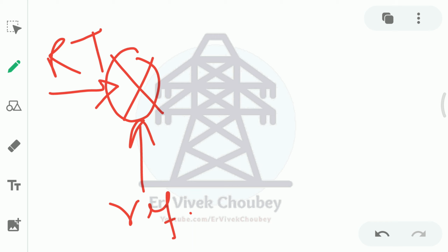Now let's say the room temperature is 25 degrees Celsius and the reference that we are setting up here is 20 degrees Celsius. So there is a temperature difference of 5 degrees Celsius, so the comparator will send a high output. That's how a comparator works. If there is a difference between two inputs that are provided to the comparator, it sends a high output, and if it is not there, it sends a low output.